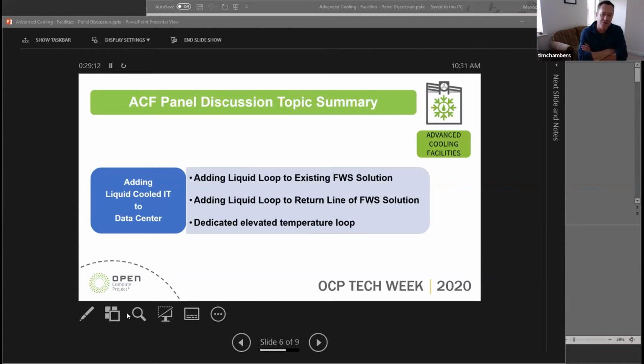The other thing we did on there as well, to keep Dr. John Summers happy, is we actually wanted to prove the PUE going out into a larger heat source. So we put dedicated pumps on there to show the PUE of this happening. And what we found was we didn't use them for about 3 months and they just locked. So again, part of the plan was, well, these pumps weren't capable. So we had to be really careful of what equipment we put in there, because some of this kit is not made to, I suppose, move around as much as we'd like it to do. And it's something we are doing testing on at the moment to make sure we don't fall foul of this on bigger installations.